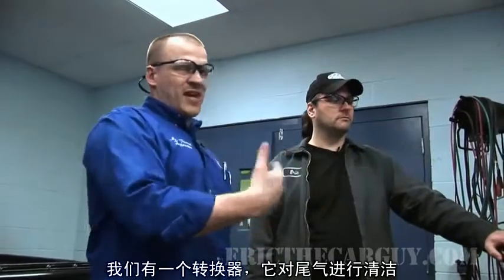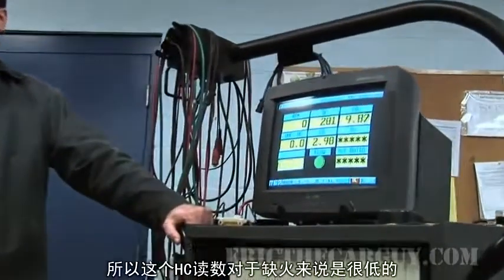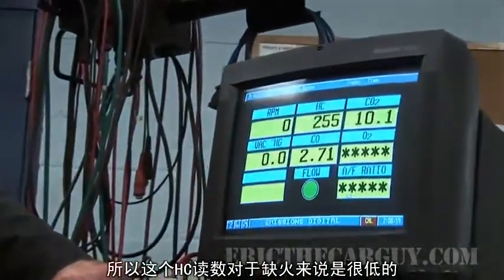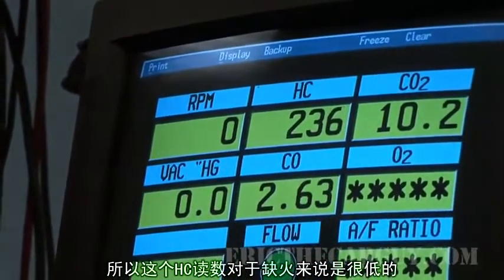And again, this test isn't foolproof because we have a catalytic converter that's going to clean up the emissions, and using these hydrocarbon numbers with a cat in play, I got to tell you though, those are pretty low for a dead misfire, even where we're at right now.